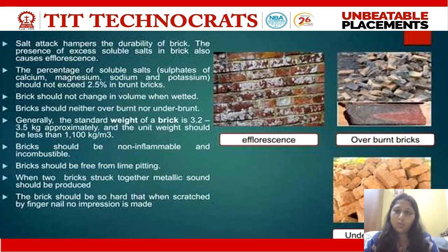So burning means what? The molded clay is heated so that it gets hard enough and gets its strength. But the burning should be done in proper amount. It should neither be more nor less, because underburnt bricks would not give us more durability. They would break down, they would not take more load, and overburnt bricks may also have weaker strength and weaker properties.